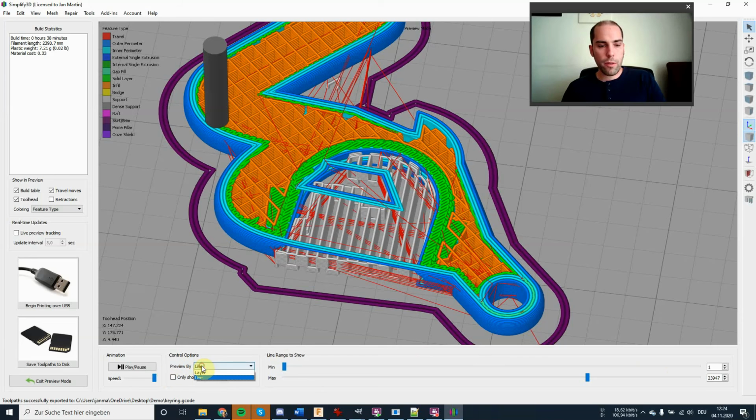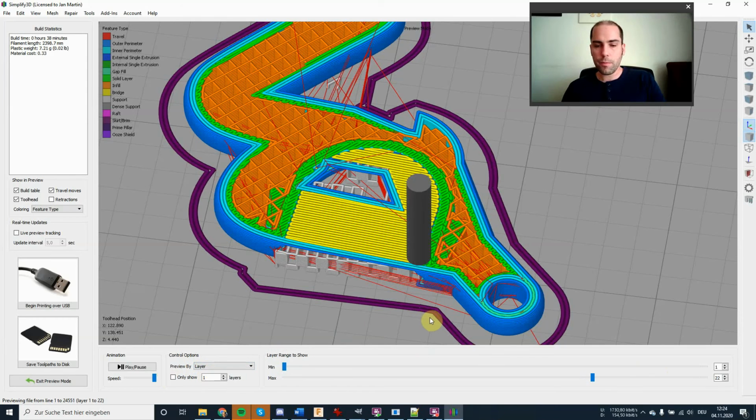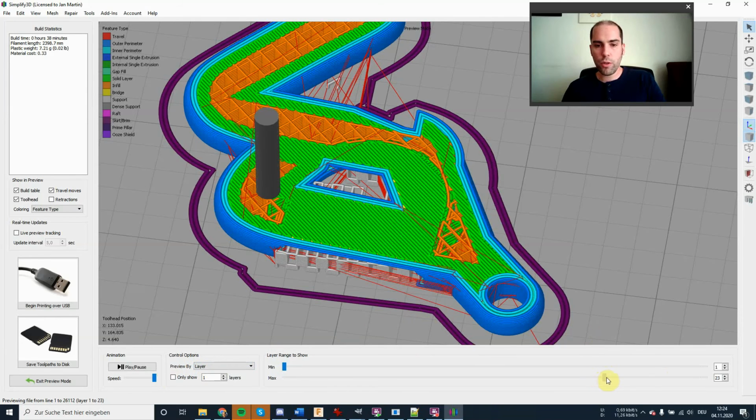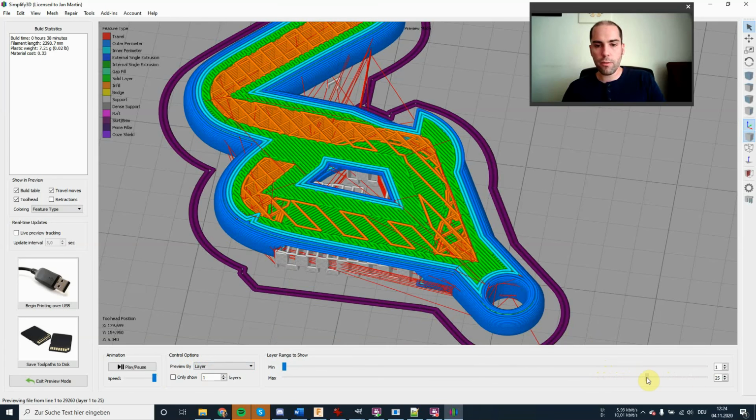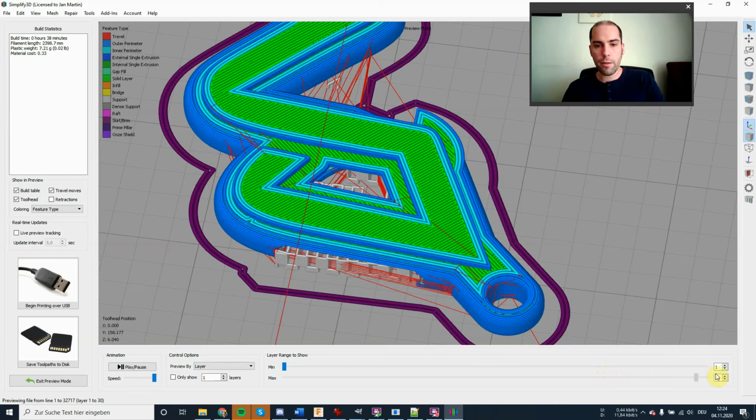We have to take care of one thing, because we want to have two colors, right? We want this in white and then the logo in green. So we will need to change the plastic that we're going to be printing with. In order to do this, we need to insert a pause command into the G-code file that we just created, and we need to look just where to put it.